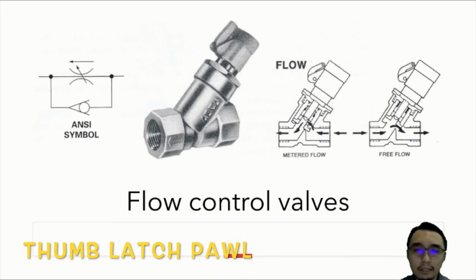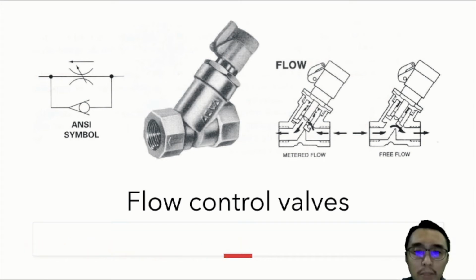The valve bonnet is scribed with graduations to serve as a position indicator for the stem. When the pawl is in the up position, it creates a friction lock on the knurled bonnet and the knob cannot rotate. When the pawl is at 90 degrees to the knob, the knob is free to rotate. Mounting in any position will not affect operation.